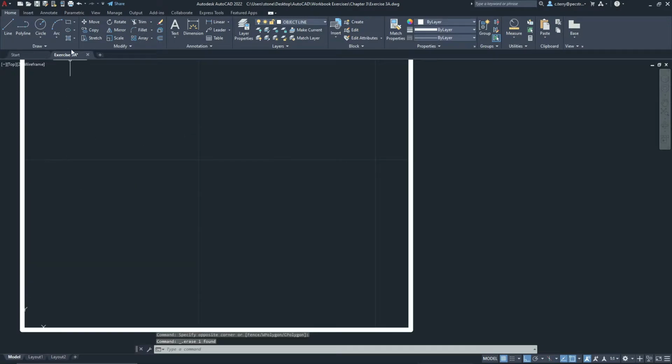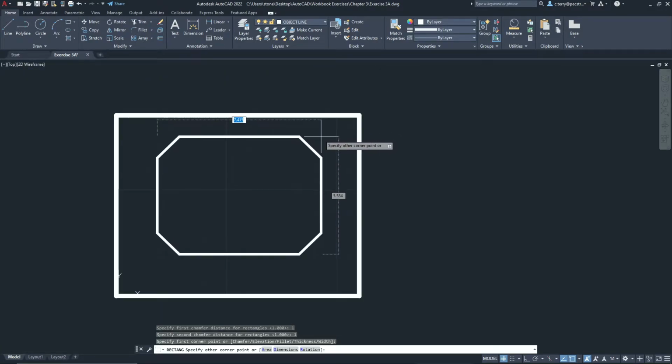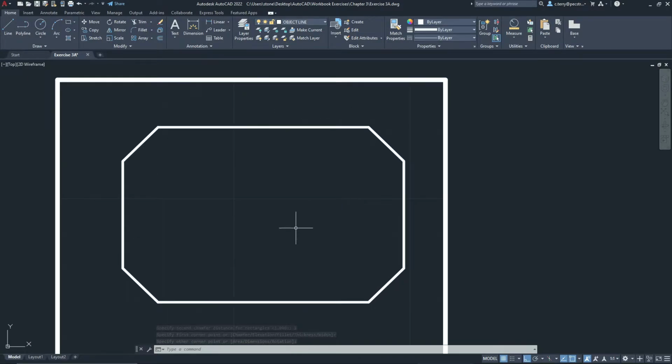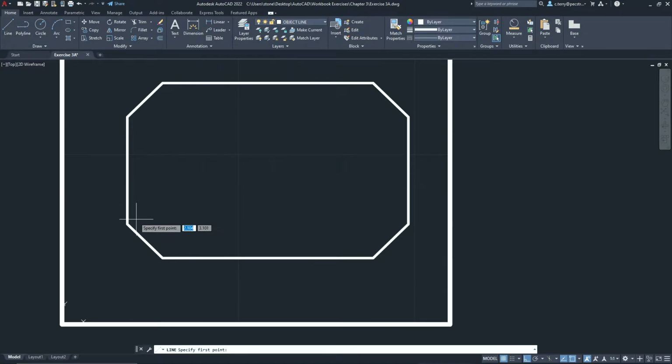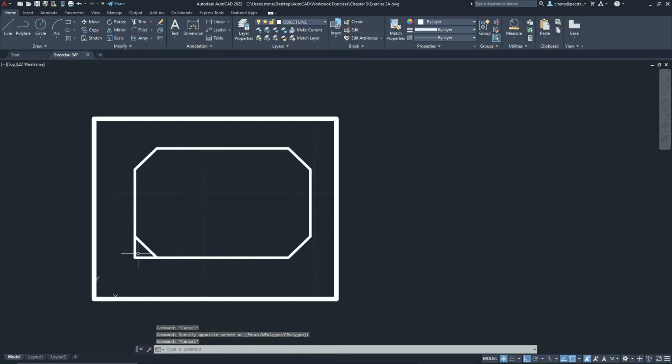and then I specify my corner point from there up. Whoop, hang on, I did that wrong. Back up. All right, chamfer. We want the chamfer to be 1 and 1, and then when we draw a rectangle now, you can see the chamfer is around all 4 edges. And what that is, if I were to come here and draw a line, if I say 1, draw another line and say 1, it chamfered that 1 inch and 1 inch on all 4 sides.